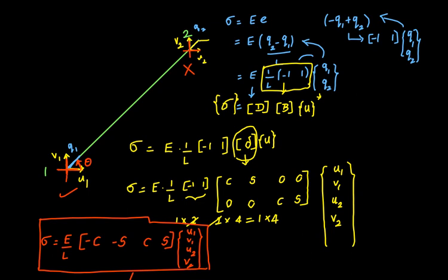Out of 1 and 2, which one is the least one? It is 1. So suppose you are marking the nodal points this way, 1, 2, you put the coordinates here and measure it in this direction. So that's going to be your theta. All right. So why do we do that? Because you just want to be consistent so that in your assembly, there is not going to be any mistake when you solve the problems.